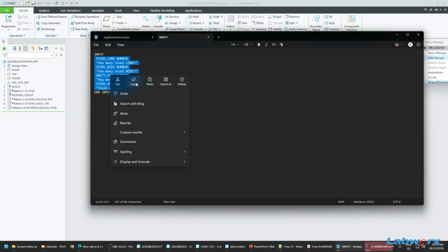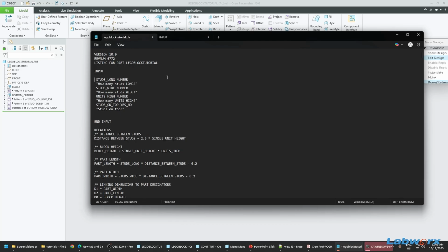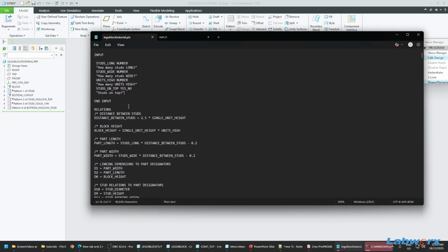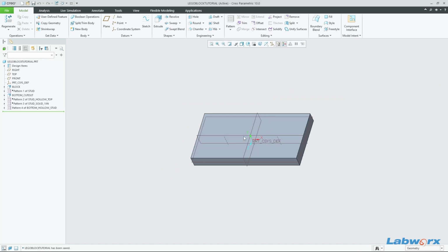So I'm just going to copy that and paste it into my file. You can ask whatever you like really here, and it'll set those parameters. And because it's setting those parameters here, it's going to continue with those values rather than trying to use them from our parameters window. So now that that's pasted, we can save and close, and we go yes. And we're just going to go current values for the moment and hit done and return.